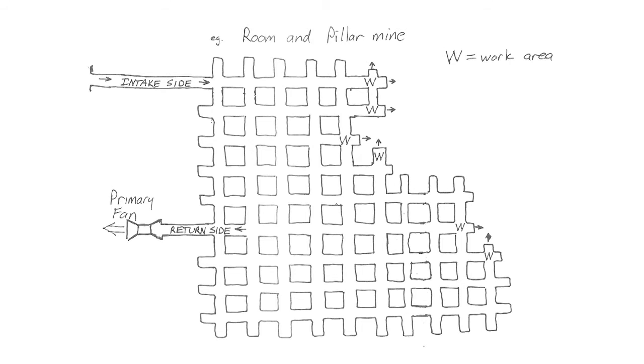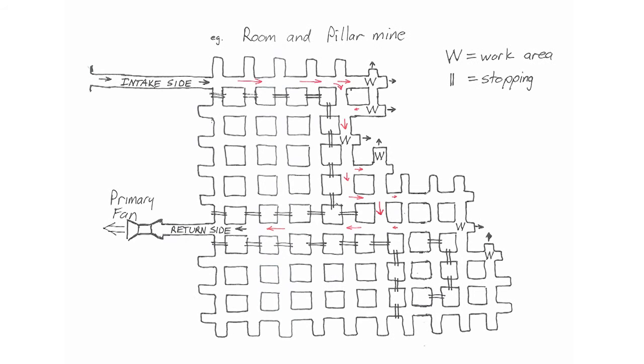As a mine develops, the extent of open underground space increases. However, only current work areas need to be well ventilated, and abandoned areas reduce the efficiency of the system. To control where the air goes and how much gets there, disused areas and shortcuts are sealed off by stoppings. These are walls made of masonry, concrete blocks, timber, steel, etc., erected across openings to direct or channel flow.